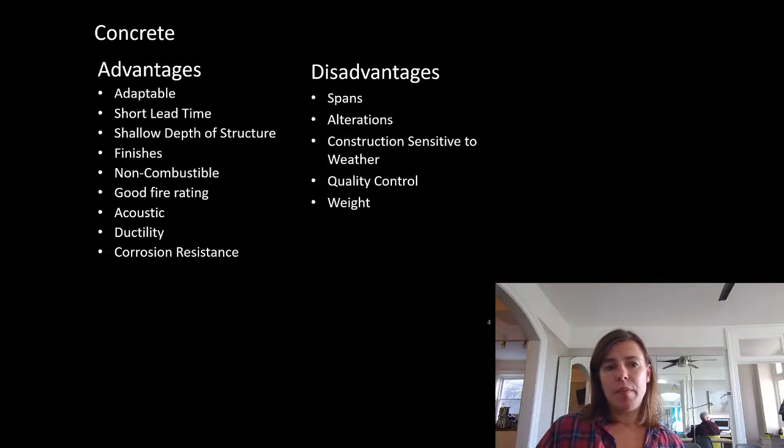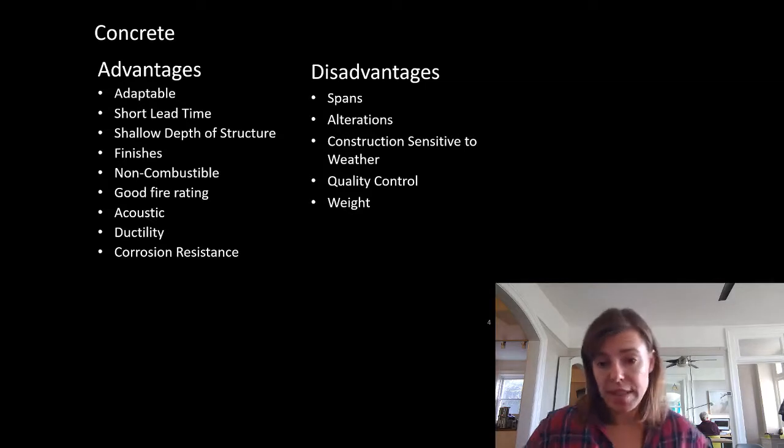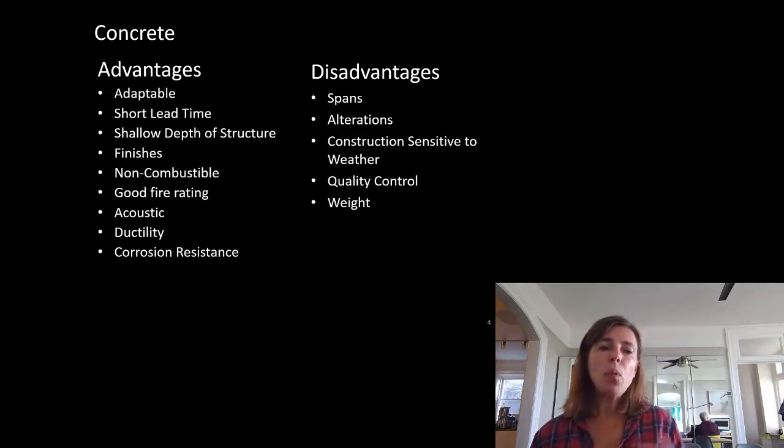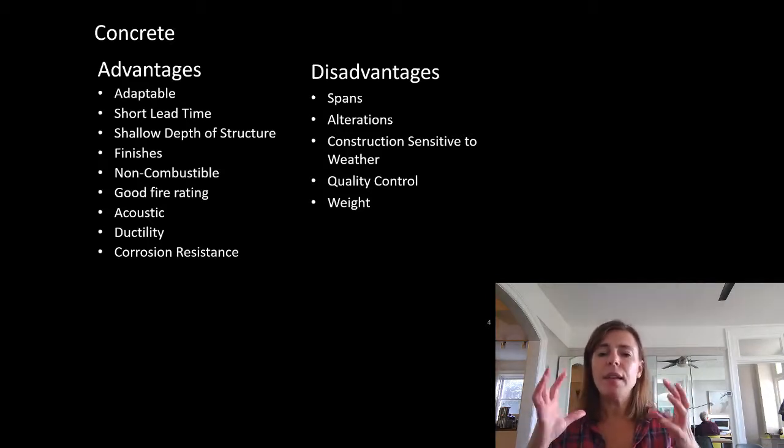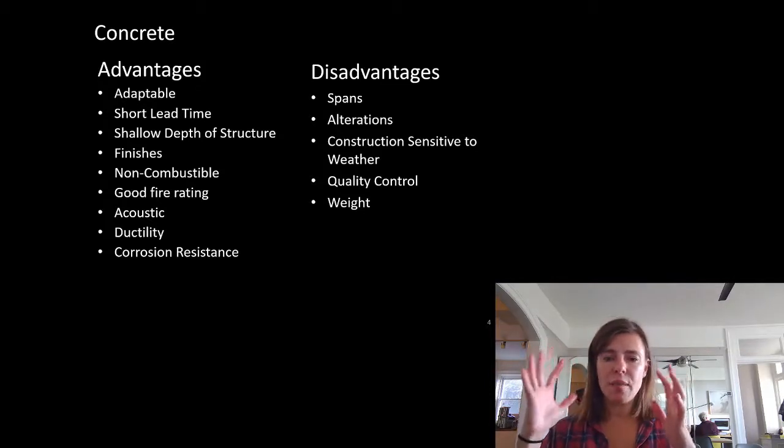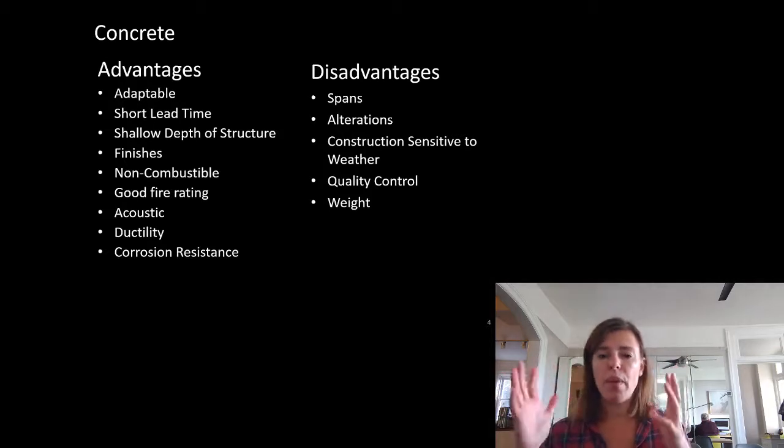Acoustics. Concrete can have very good acoustics. It's ductile, which most people think concrete isn't, because the material concrete itself is quite brittle. But when we're talking about concrete in engineering, we are not talking about concrete all by itself. We are talking about reinforced concrete. That means there is steel embedded in it. Now, ductility is when you put a load on something and it moves, and you can have large movements without it failing. And that's the definition of ductility.